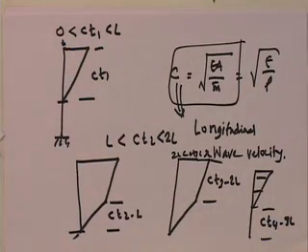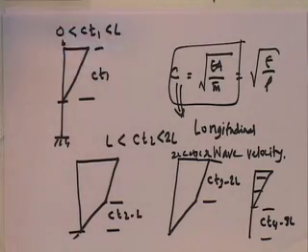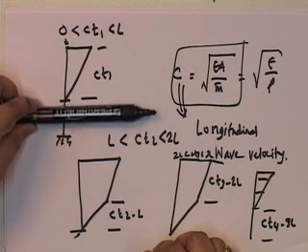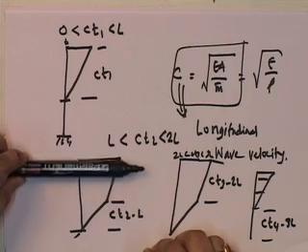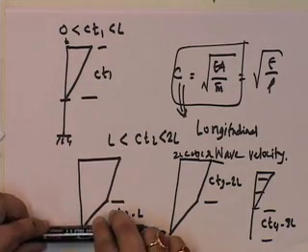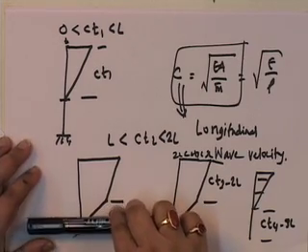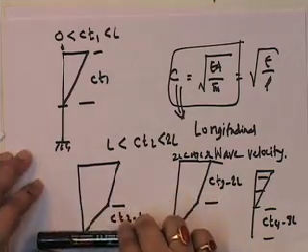So, if you look at the actual thing, when you suddenly apply the load, this wave travels from here and comes here and gets reflected. When it gets reflected, you have a combination of a wave traveling this way and a wave traveling this way.